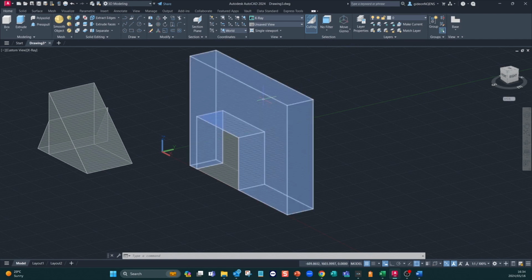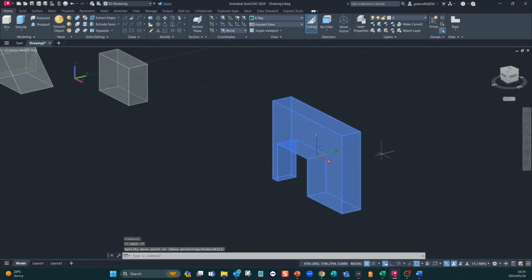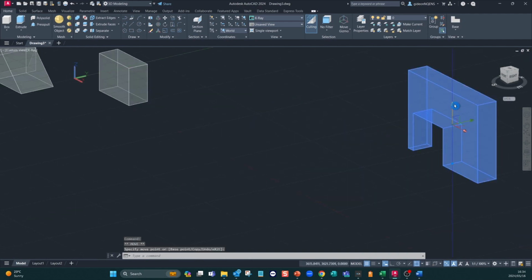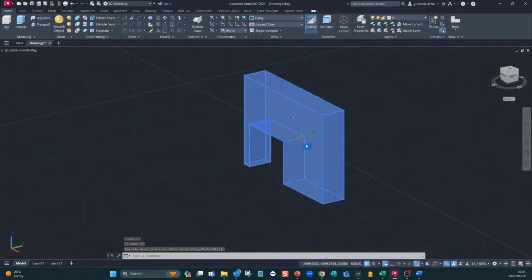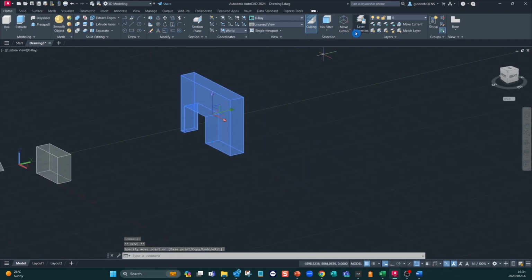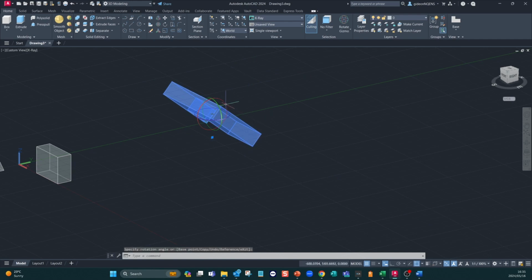What that means is, if I'm just going to choose the top one for instance, you'll notice all the different axes that I can move that specific object. So if I zoom in, I can move this in all the different directions with alignment of the Z axis. When we go to the rotate gizmo, you'll notice we'll be able to rotate along the specific axis as required, and we can specify the rotation angle as needed or required.